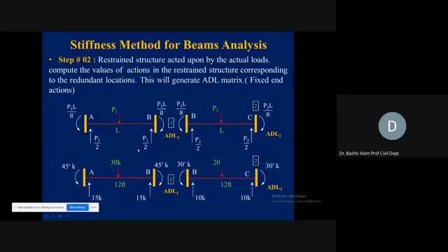Then you can find the reactions due to the unbalanced moment and the distribution of the load to the supports. With the help of those, you add them up algebraically, and whatever values you get there become your reactions. Now, this was for the point load that we discussed. Now if you have a UDL, let's say this UDL is applied throughout the span.